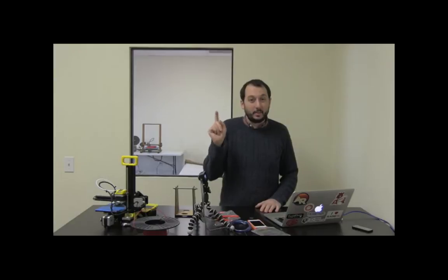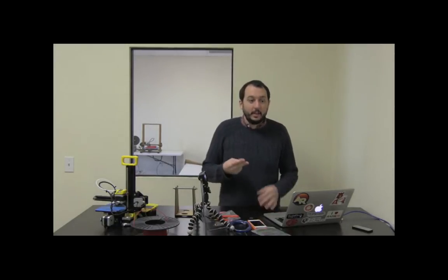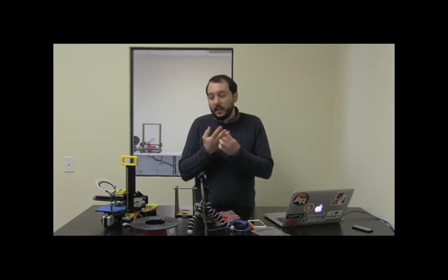So we talked about there are 4 main troubleshooting things. The first one is to make sure that everything's plugged in. You can inspect it, and I think you guys did that a little bit before the video went out. The second one is Cura settings, which we just went over, to make sure that all those are set. Because sometimes if Cura isn't set up right, something might be weird with it and it might not work. But we got that set now too. The other 2 are making sure that the filament isn't clogged, and by doing that, we'll load it right now and go over that step. And the last thing is we'll make sure that the build plate is level.